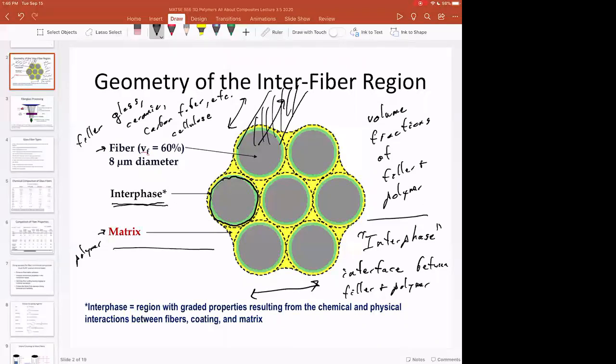And so when you read the composite literature, you hear about phenomena such as adhesion, compatibilization, dispersion, etc. Because when you're mixing two materials together, those are the things that you have to worry about. If you can imagine like a fiberglass sailboat, if the glass fibers didn't stick to the vinyl ester or epoxy resin that you use, it would not be as tough of a material because you don't get that reinforcing effect. Or in lots of instances, if you don't have a good interphase, you can't get this composite effect that we just spoke about. So I have a few slides here talking about what that interface is and some things that you should be aware of as you start to specify a composite.